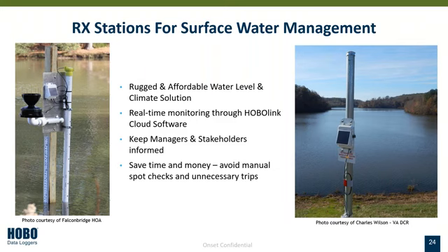Other solutions that we have using our real-time data loggers is the surface water management, right? Not all of you here connected to water resources are going to be dealing with groundwater applications. Some of you need to monitor lakes, rivers, streams, and we have you covered with that as well. You can see the two pictures here. These are RX2100s with a water level sensor. So the water level on both of these is installed into a couple of lakes, and they're doing real-time data management. So you're able to see how much water you have.